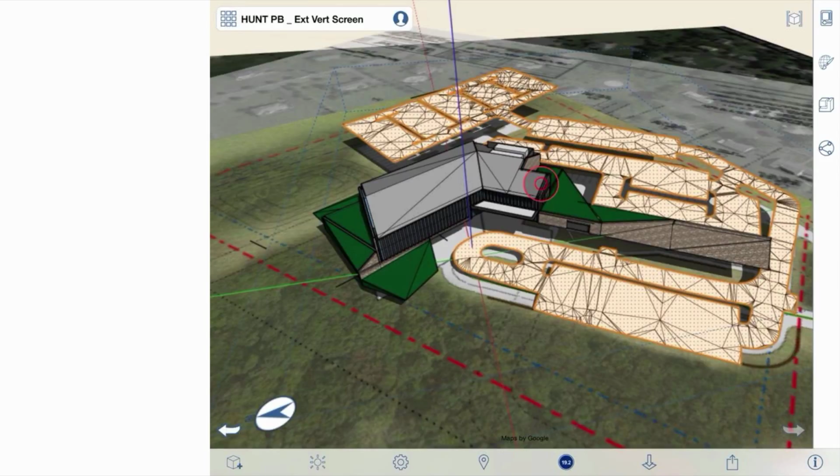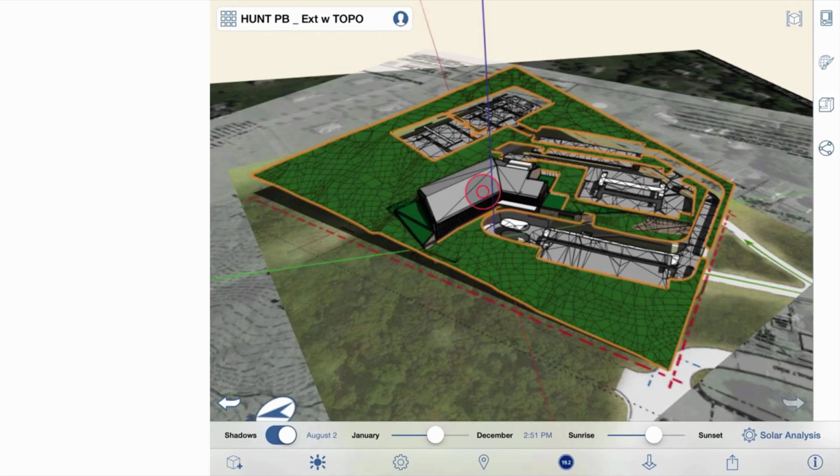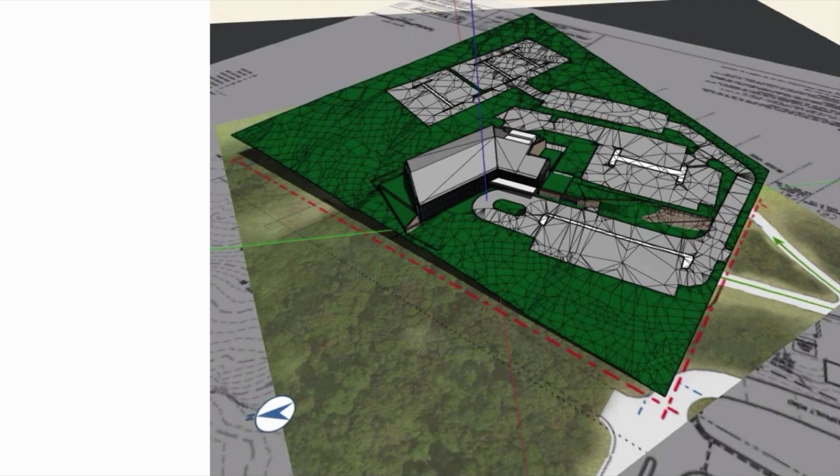It's about 27 meg, and over LTE, it takes about a minute and 10 seconds to bring something like that in. And you can see that triangulated geometry comes in at the correct location from the Rhino model now. So we went FormIt to Revit to Rhino, back into FormIt again to create some geometry. And that's bringing in the actual site.